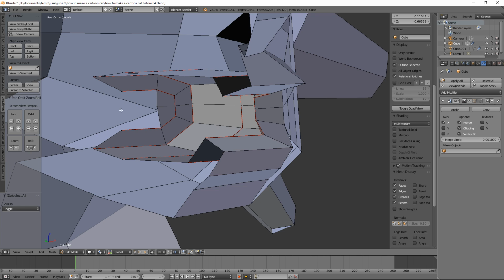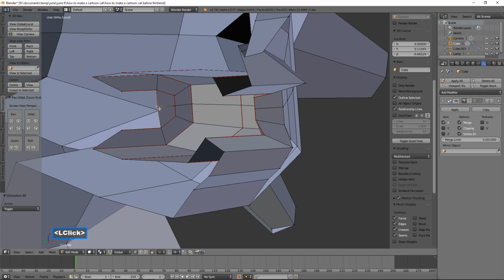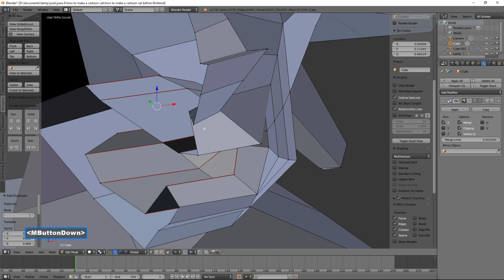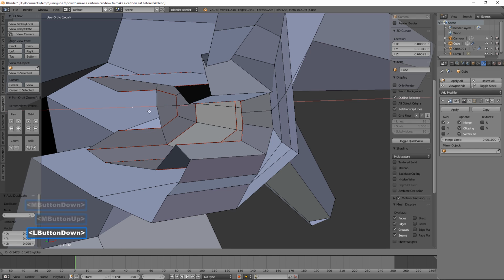Okay, I see I need another vertex here, so I'll click here, hold Shift, then press D. Duplicate. I duplicated that vertex. I'm going to click here to bring the manipulator back. I'm going to push this over here. I'm then going to press A to deselect.